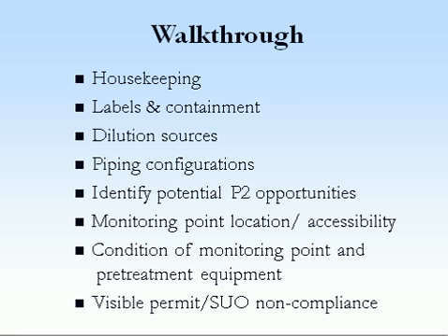Piping configuration. Do they seem to be leaking? Is it traceable to see where those pipes are going? In some cases, in old buildings where they've added on, pipes can be going every which direction, and they can be leaving the building going in different directions. So if you're only taking a sample in one location, you might not be capturing the entire representative sample for that industry. You might need to take samples at more than one location.